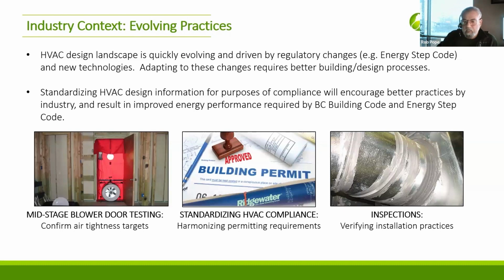Some of the evolving practices happening in the industry would include blower door testing. Now, there are a lot of jurisdictions across the country where you're required to meet a certain air change and infiltration rate, right? And the only way you're going to know if you did it or not is to do a blower door test at the end. That has been a requirement in a lot of jurisdictions for a long time. But what has started to become a requirement, and what's always been good practice, is you test it mid-construction so that you don't have to worry at the end when everything's painted and maybe the furniture's already there.